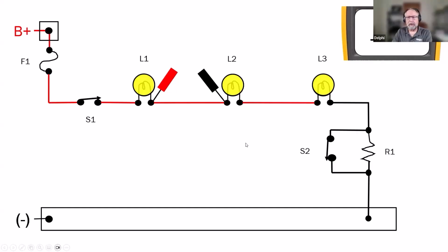And on the boards that I use, 1.7 millivolts is a number that would be expected on this, say for a 16 gauge wire with maybe 2 amperes flowing through it. Regardless, this is telling us that there is current flowing in the circuit with that potential difference going on, not source voltage, right? But potential difference of this magnitude is telling us there is current flow in the circuit.